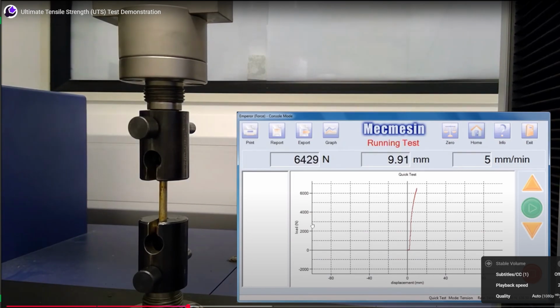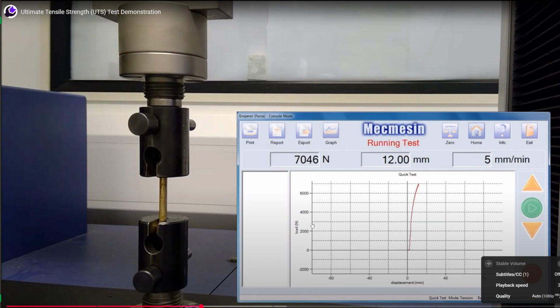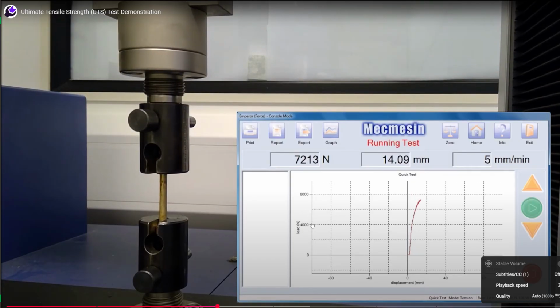And so you're going to see it's slowing down and the curve becomes less linear because basically the material itself is changing and morphing as you're pulling it. So if it let go, it wouldn't restore itself anymore. It wouldn't go back to its original form. It'd just be stuck bent. Think of it like crushing a can. You will not restore it to its original form anymore.